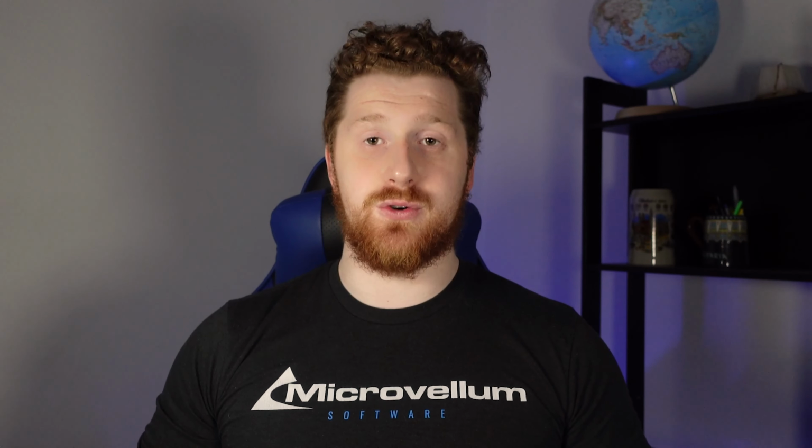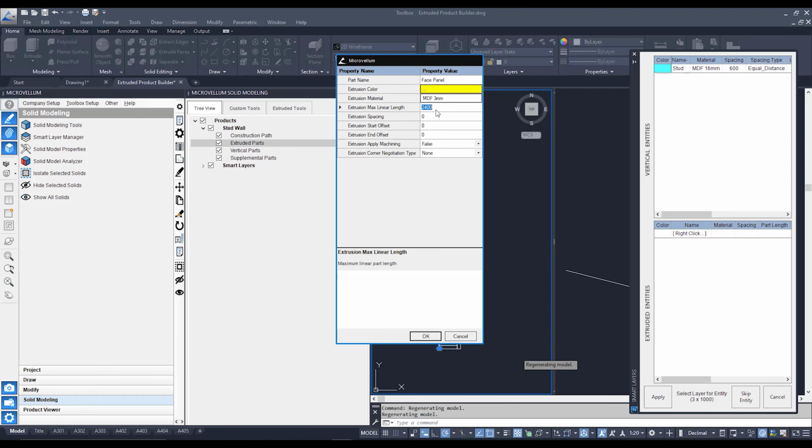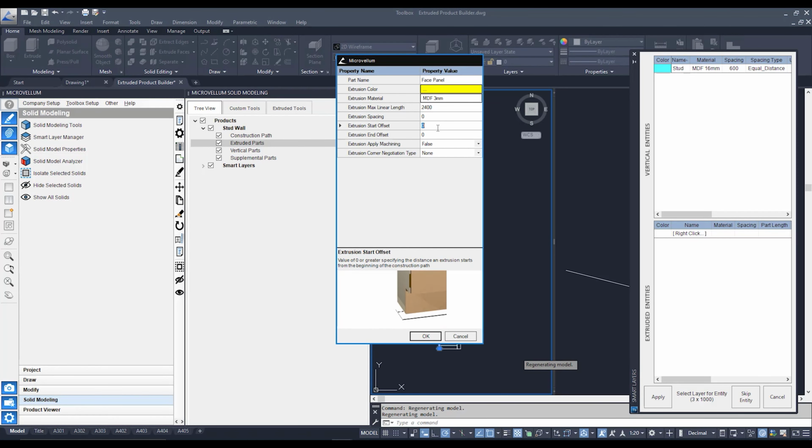This is pretty much saying at this dimension here, we're going to add a break. We're going to add a break between two extruded entities. We don't want our extruded entity to exceed this length. Extrusion spacing, this is pretty much saying, well, in between those breaks, in between those linear lengths, we can actually offset, we can have a little bit of a gap between those extruded entities. We can also say we want to start or end an offset within our construction path, maybe overhang our panels across the start and end of our construction path.